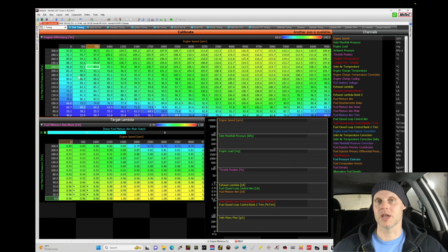This expresses the percentage of cylinder filling at a given RPM and inlet manifold pressure. This essentially is estimating the air mass or airflow coming into our engine. If we had a mass airflow sensor, it would actually measure that amount of air mass, or the airflow coming into the engine. So we need to put values in the table here that make sense for a starting point.